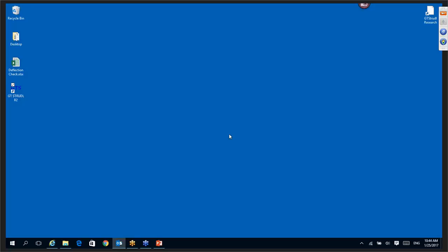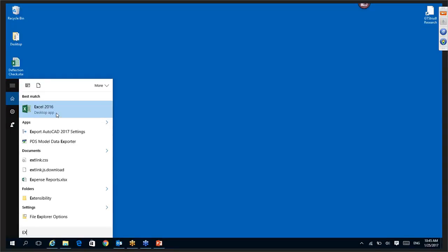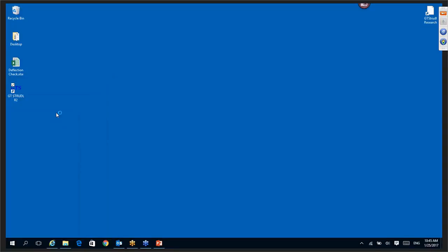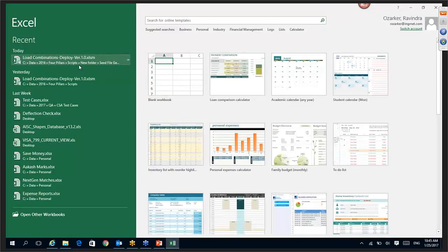Okay, but what I'm saying in this presentation is sometimes that's too much information early on when you don't know that the structure is going to pass with linear static analysis, okay? But now we've taken care of those problems. Now we want to do a real analysis. What I have done is I have written an Excel macro that'll generate these combinations for you, okay? Now this Excel macro, Aaron is actually going to distribute it to you all after the presentation. You can download it and you can test it out.